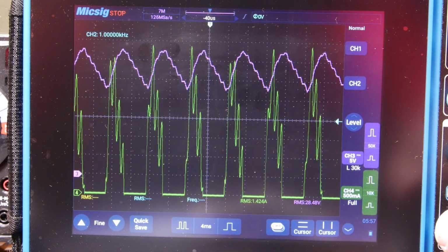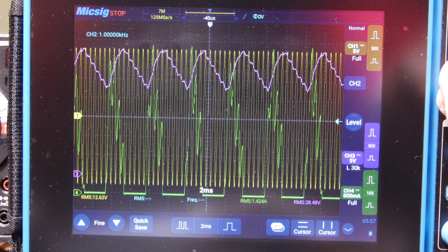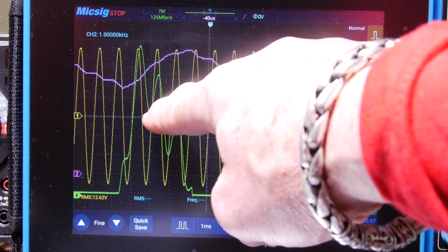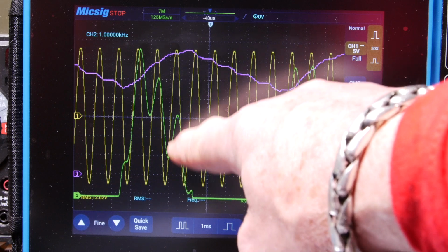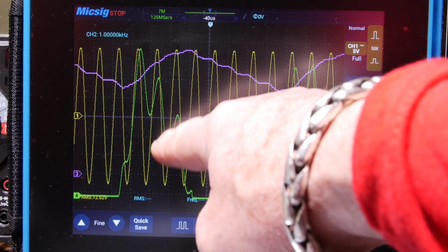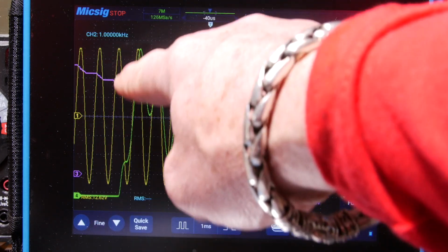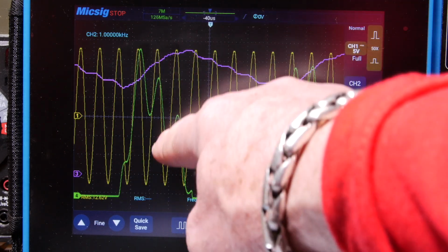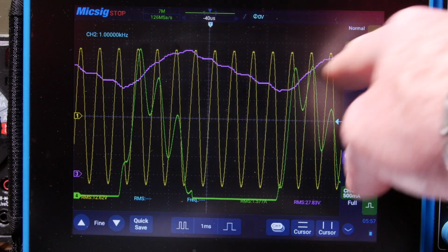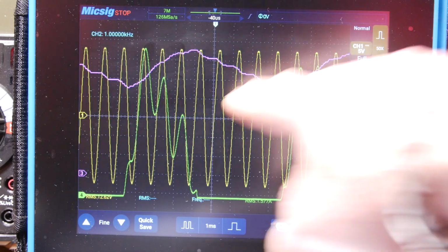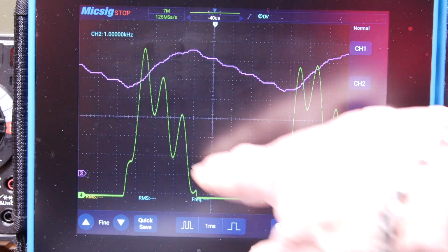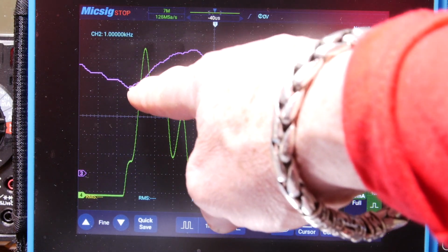I'll spread it out so we're just looking at one of those. You can see every time we get a waveform, it's pulling current through that transformer. So instead of just getting a charge into the caps, we're getting this plus the current going to that signal. The other thing we should note is the voltage. See how far it drops?